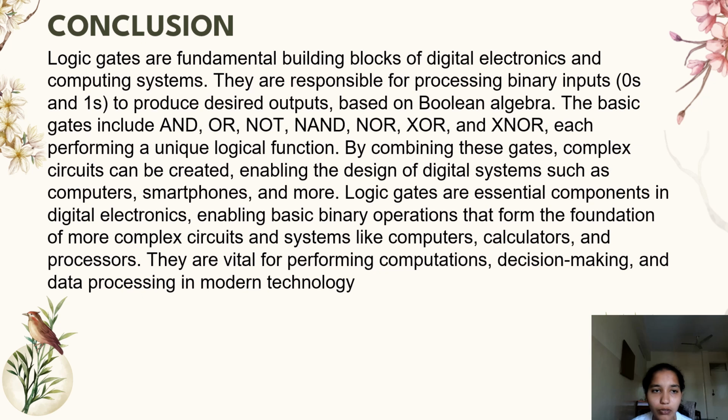I finally conclude that logic gates are fundamental building blocks of digital electronics and computing systems. They are responsible for processing binary inputs to produce desired output based on Boolean algebra. The basic gates include AND, OR, NOT, NAND, NOR, XOR, and XNOR, each performing a unique logical function.